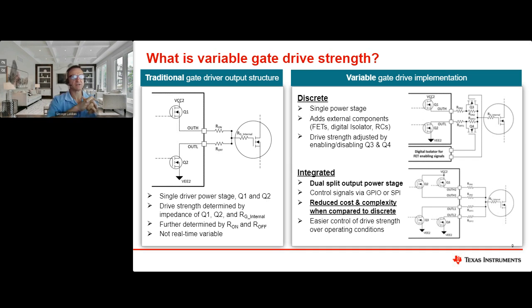In this particular product, we actually offer you 2 ways to control the drive strength. One is through the 4 megahertz SPI bidirectional bus. The control will be coming from the MCU. But we also give you the ability to set the drive strength at power on without the SPI bus, by using 3 digital input pins that we have. It's essentially a lookup table that would be loaded from the MCU also. And you'll immediately be at the drive setting of your choice at power on without having to use the SPI bus.